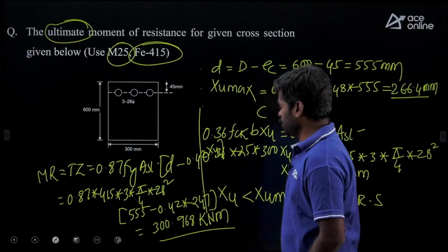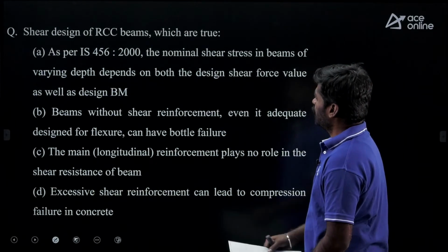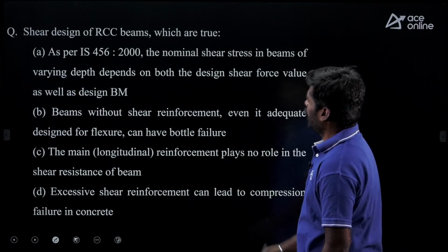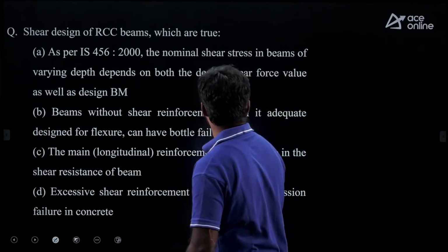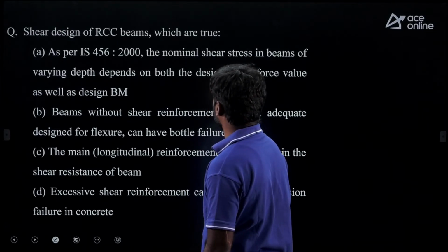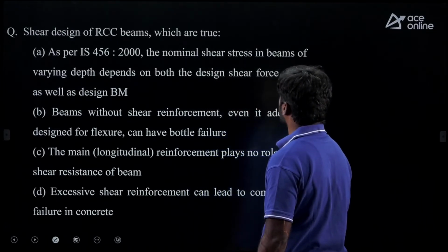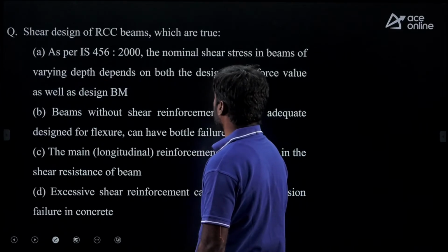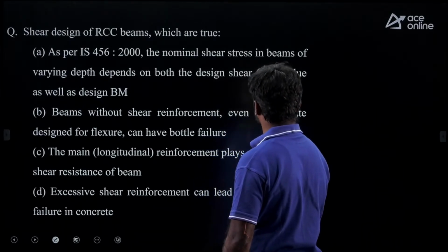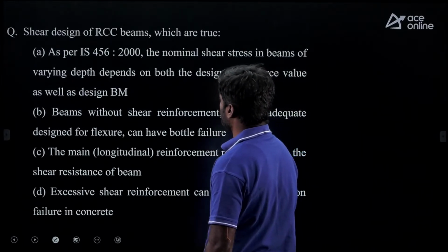Then move to next question. Shear design of RCC beams, which are true. Given 4 options here, it is an MSQ type question, my dear. As per IS 456-2000, the nominal shear stress in beams of varying depth depends upon both design shear force value as well as design bending moment.